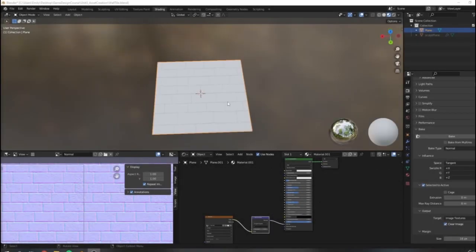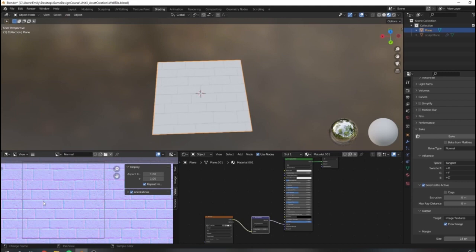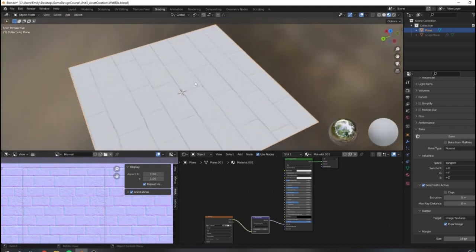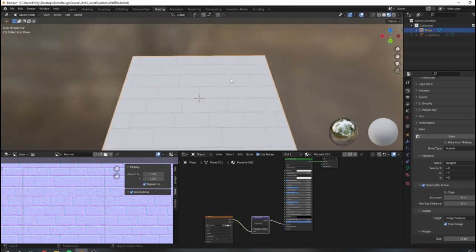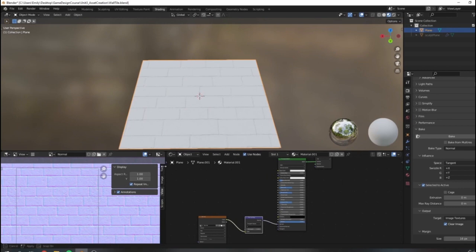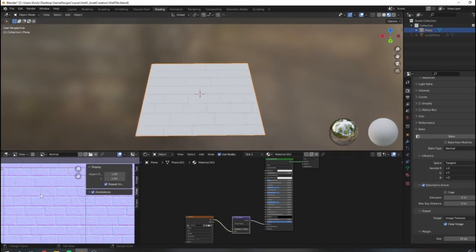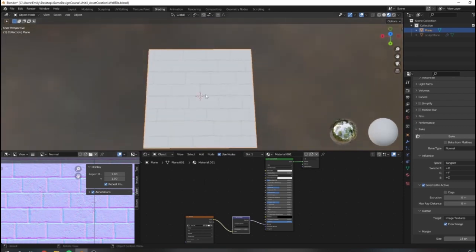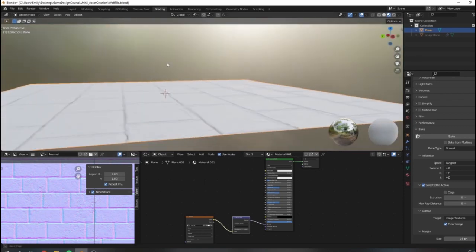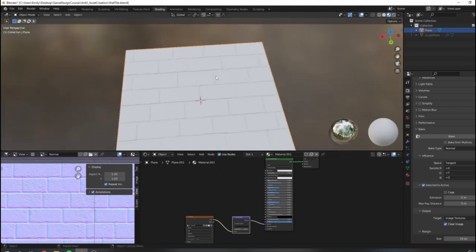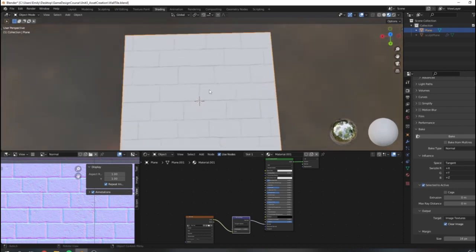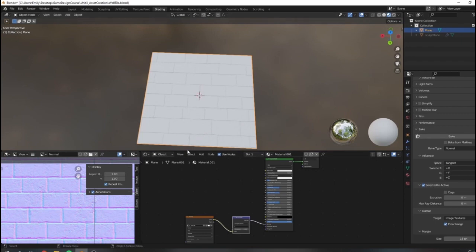All right, so when we last left off, we had just created our normal map. Now, we're gonna get into further developing the surface appearance of this. And the first step I wanna take to that effect is by baking one more type of map called ambient occlusion. So just as the normal map tells Blender, hey, this is how light should react with our surface, ambient occlusion tells us where we should draw in our shadows. And it just adds a little bit more depth to our pieces. So we're going to use a pretty similar baking process here to achieve an ambient occlusion effect.